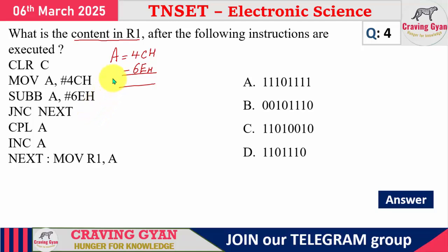Now look at the things. Whenever you have performed a subtraction of a higher number from a lower number, what scenario do you get? The carry flag contents will be equal to 1 over here. Now look at the things. What is the value of 4C minus 6E?